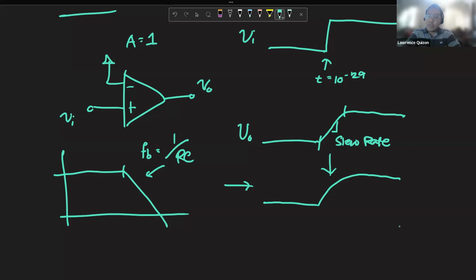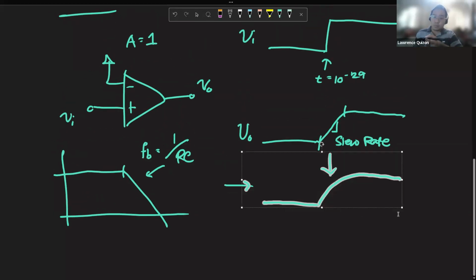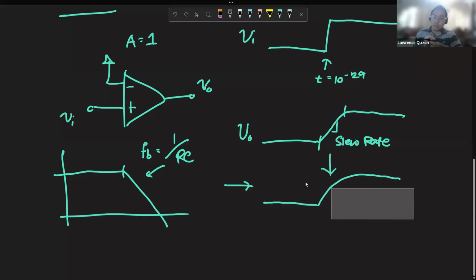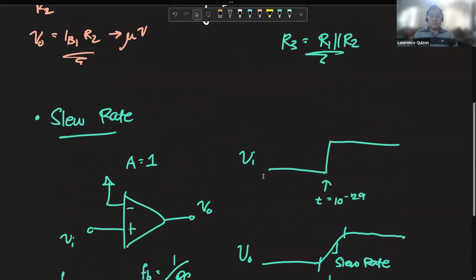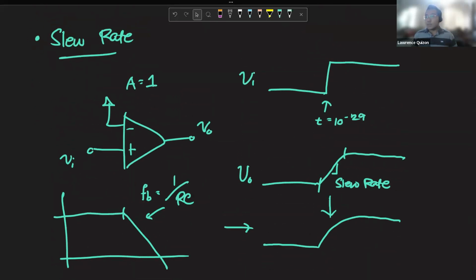So, that means that this non-linear non-ideality is actually related to a linear non-ideality, right? It's just called a non-linear non-ideality because it causes non-linear distortions in your output, no? As in, well, of course, no, this is exponential, it's not linear, right? So that's the slew rate, no?